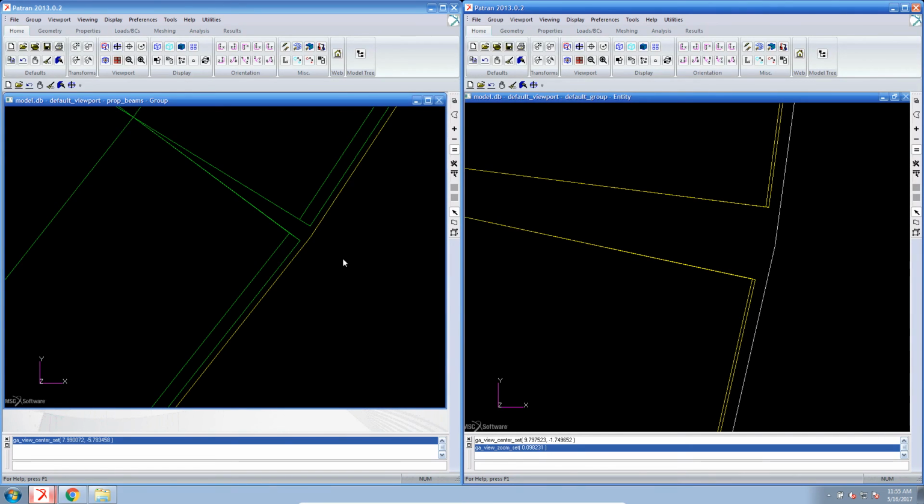And we can do other things like viewing the results. What's the buckling mode shape look like for this new result on the left and the right? What are the beam stresses? What is the von Mises stresses? Have I really satisfied all the design constraints? I leave this up to you to go about doing this on your own just to make sure you have the necessary procedure already established. And now I think I'll go ahead and pause it there and conclude this tutorial.